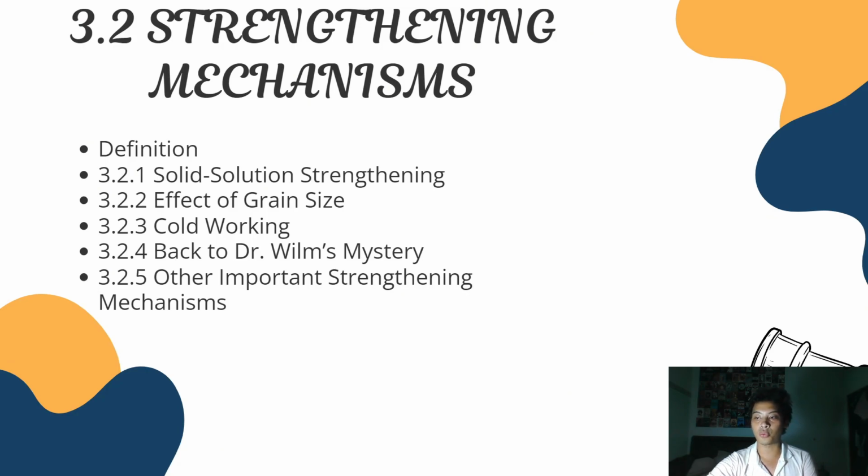First, recovery, which relieves some of the stored internal strain energy by rearrangement of dislocations into a lower energy configuration without any change in the shape or orientation of grains.